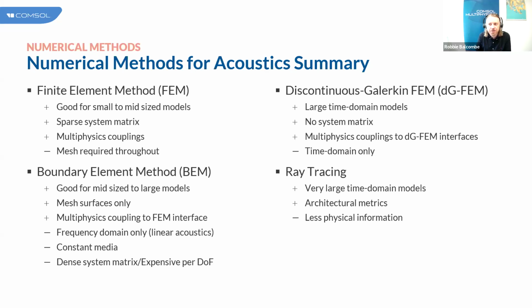So it will allow us to compute larger problems with the finite element method. However, it's only available in the time domain. We then have the boundary element method, which is good for sort of mid-sized to large acoustic problems. We require a mesh only on surfaces. And again, we can set up multiphysics problems using the boundary element method. So we can couple this to mechanics, for example.